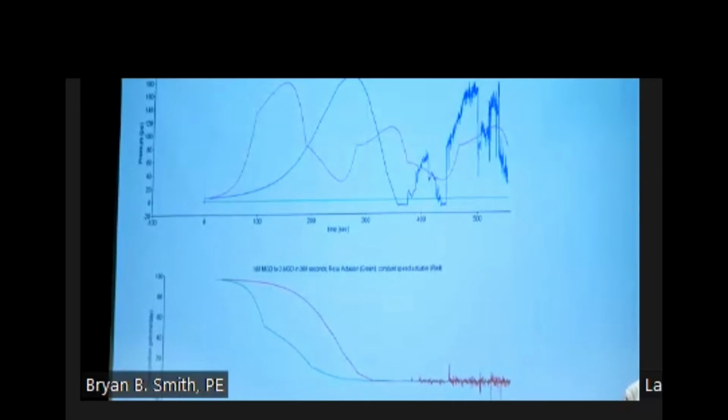In the computer model, the transient monitoring equipment, the design was gorgeous. There was absolutely no pressure transient. They did not exceed the pressure rating of their piping system, nor did they drop into a vacuum state. The valve closed in 30 minutes. Electric motor operator, stepping motor. Close, close, close, close, close.